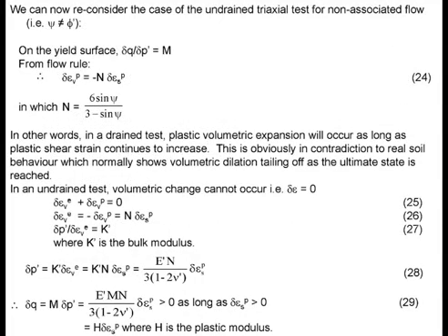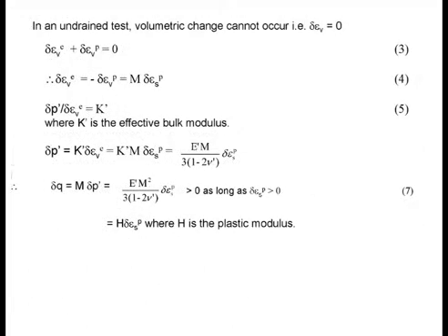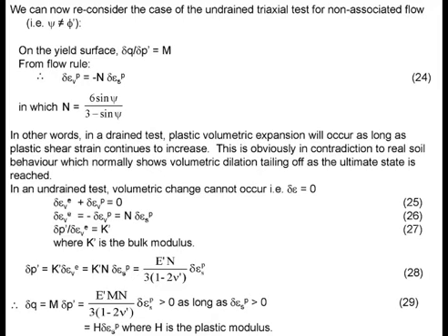That's all. And so you go through the same thing again. The rate of change of deviator stress is equal to m times the rate of change of mean effective stress, which is actually the equation of the U locus, the gradient of the U locus. And immediately you come up with this. When you compare this term with the previous term, you realize that in the previous term it's m squared, but now it's m times n.